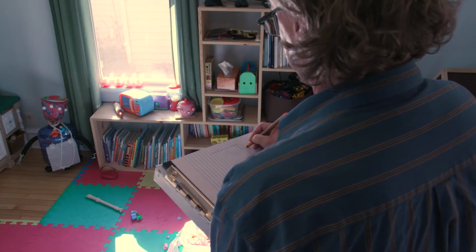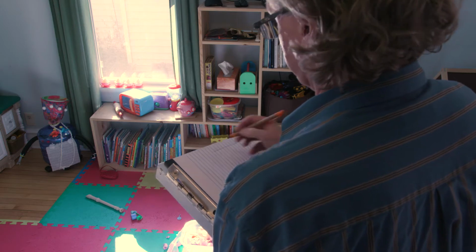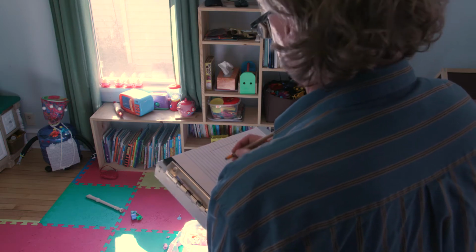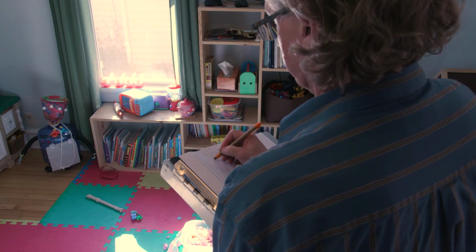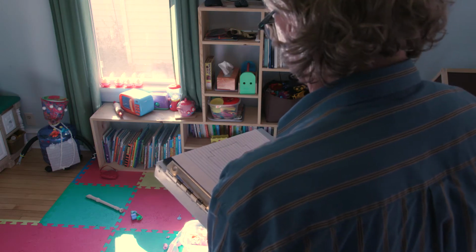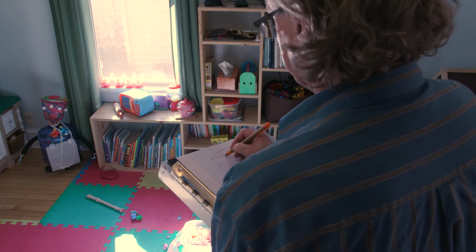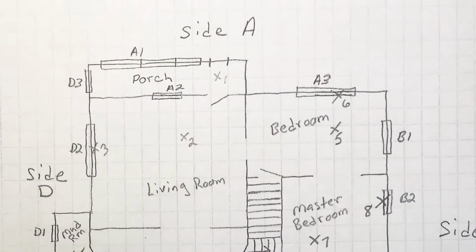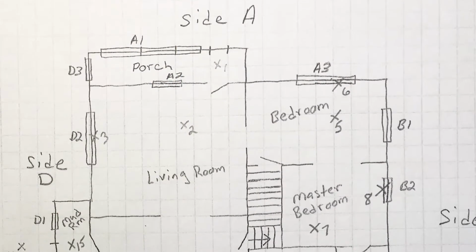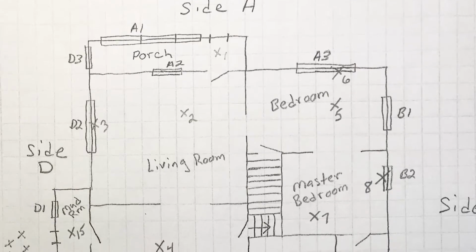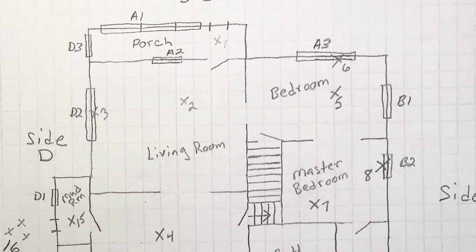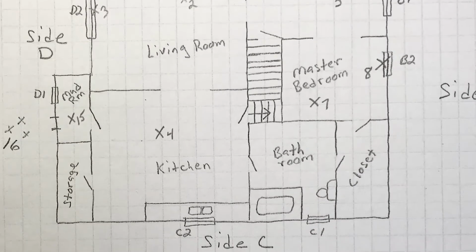Sketch out a floor plan of the house. You can do the entire dwelling at once, or you can draw a room or section of the house at a time and put the pieces together in your office at a later time to make a complete floor plan. You are required to show the location on a floor plan of each dust wipe sample and paint chip sample you collect. Each location should be labeled to match the corresponding sample ID number you assign.